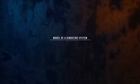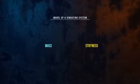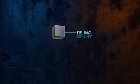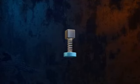The two most important parameters in any vibrating system are its mass and its stiffness. A common modeling approach is to lump all of the different contributions to mass and stiffness together, and represent them using a point mass with a mass m and a spring with a stiffness k. This is called the lumped parameter modeling approach. This kind of simplified model might seem quite abstract, but can actually represent the dynamic behavior of a lot of real systems quite accurately. The beauty of this simplicity is that we now have something that we can analyze mathematically.